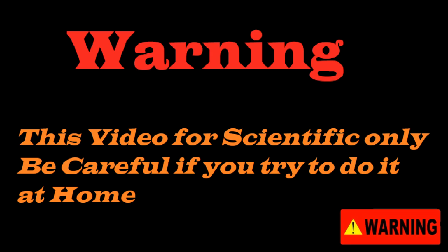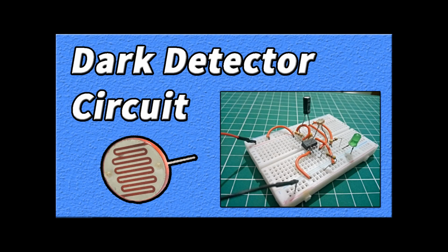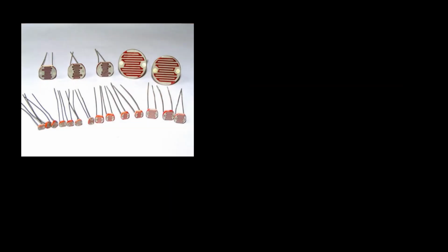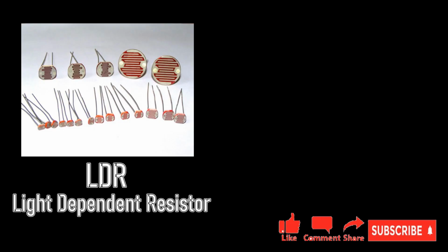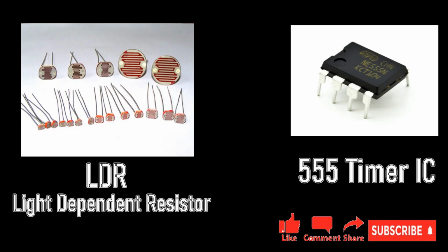Hello everyone. In this tutorial video, we will explain and design a darkness detector sensor that can be used in many applications, or used with any 220 volt devices, or just as a darkness alarm. A darkness detector is simply an LDR, light-dependent resistor, interfaced with a square wave generator. In this project, the square wave generator is developed as a 555 timer IC based astable multivibrator.